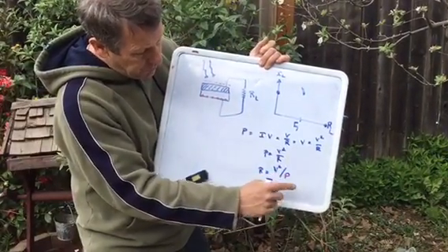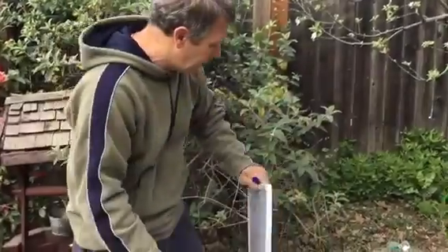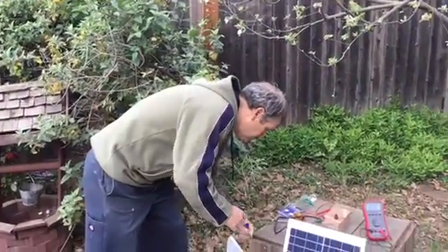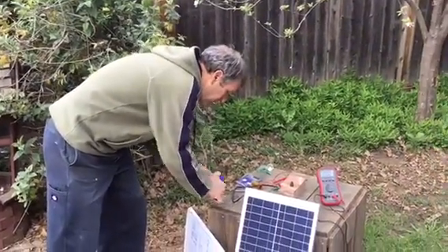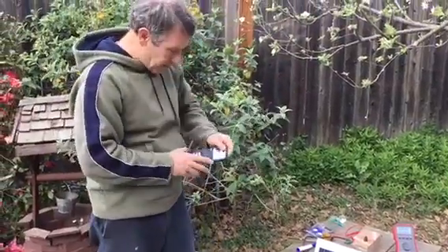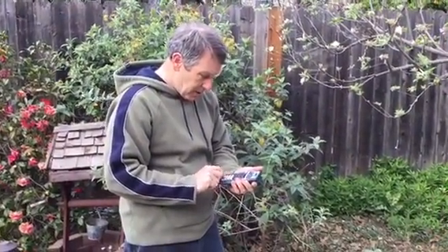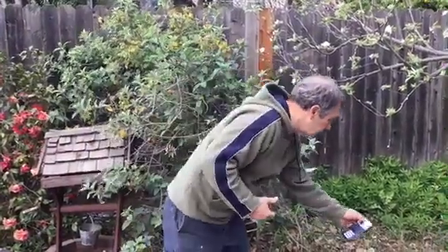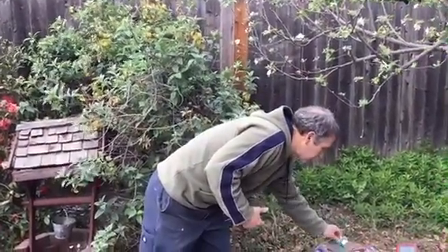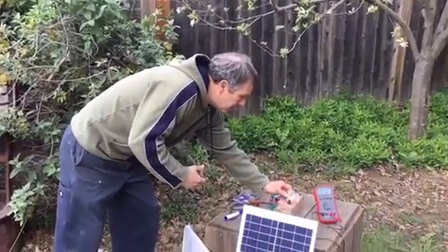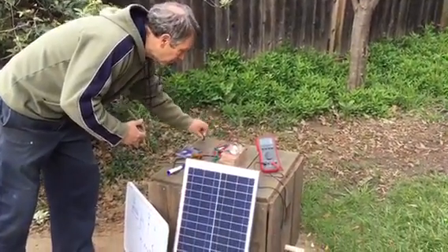So we ought to be able to do that on our calculator. We had 12 volts and we had a power of 20 watts. I'm just going to pull out my calculator and see if I got what you guys got. So I'm going to do 12 squared divided by 20, and I got that that's a 7.2 ohm resistor. So a slightly different resistor. I'm going to go ahead and put that up there.